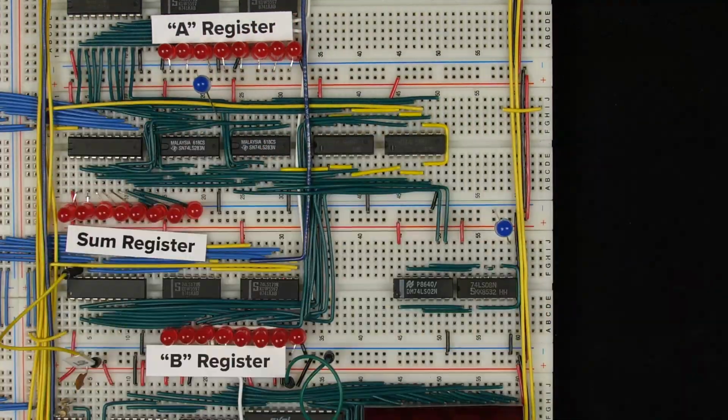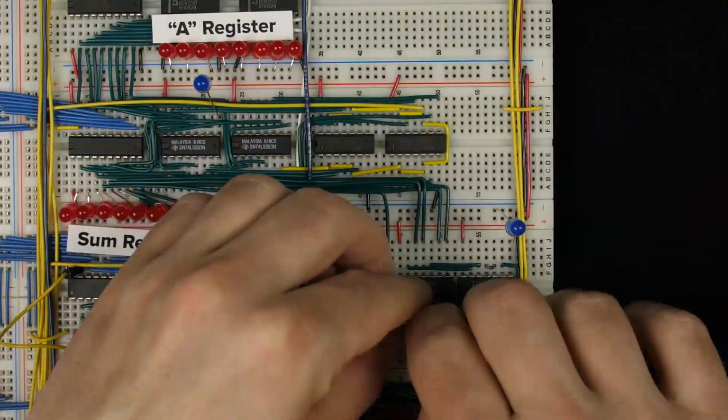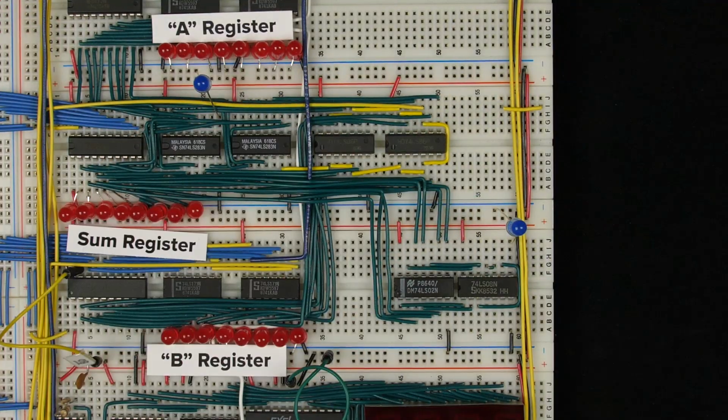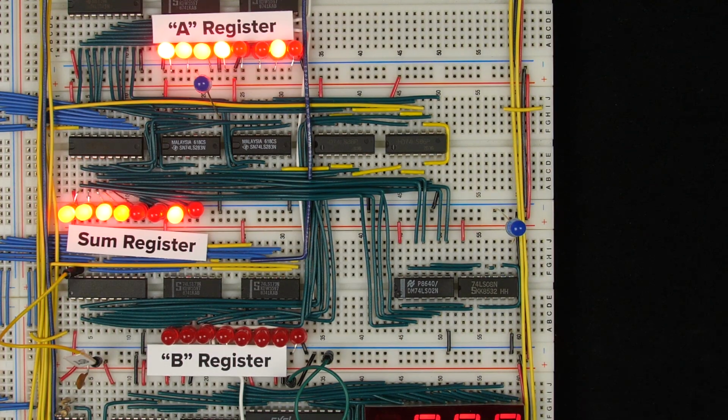So I'll hook each of the 8 bits of the sum register up to the inputs of our 4 NOR gates. And it doesn't really matter which bit goes to which input or which gate, since we're really just trying to tell if they're all 0, so it doesn't matter what order they're in. Okay, now that's all hooked up, so if we hook up power here, we can see that the output is on. So the 0 is on, which is good because we've got a 0 here in the sum register. So let me put something else in the sum register, and we see our 0 signal turn off, which is good. So at least initially, it seems like it's working.